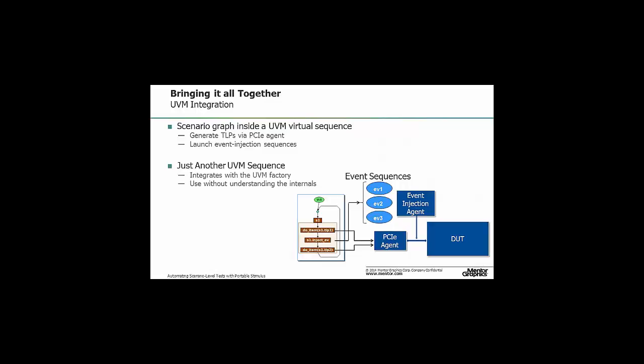It integrates with the UVM factory, and someone writing a UVM test can use this without knowing anything about portable stimulus or graphs or anything like that. It's just another sequence that you can call from your test. And it talks to the sequencer in the PCIe UVM agent.